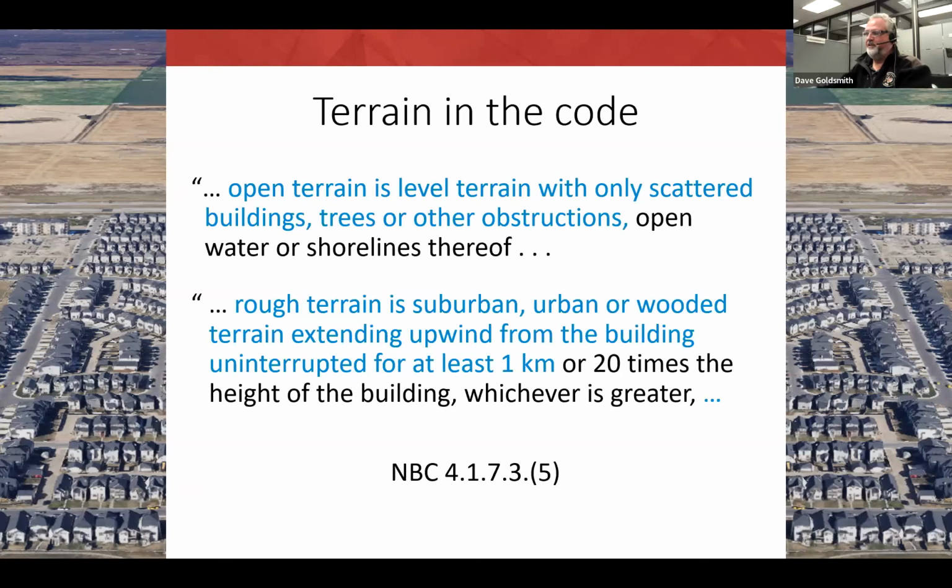And you know what? I have done that calculation, and it's actually 100 meters from the shore, 200 meters from the shore. Let's say on the shore is an exposure factor of 1. Rough terrain is an exposure factor of 0.7. It doesn't start to climb towards 1 until you're within like 300 meters, 200, 100 meters of the shore.